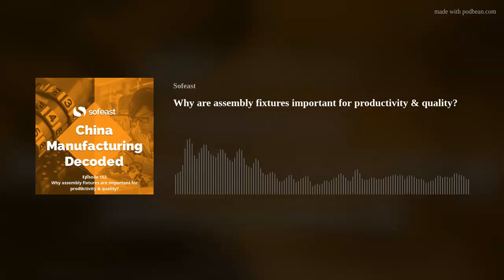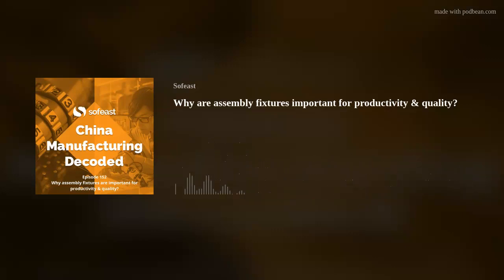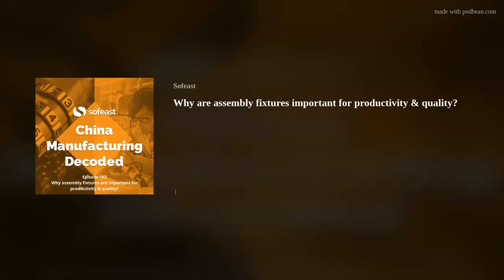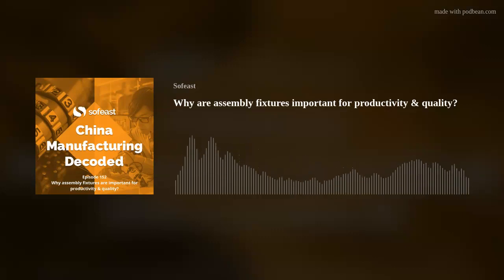Well, the idea basically is that you still take the product or the part and you put it into a fixture, and that fixture is going to help you determine if the product is okay. And a lot of that usually is dimensional. Not only, it can also be a function check and so on, like a full testing station, right?